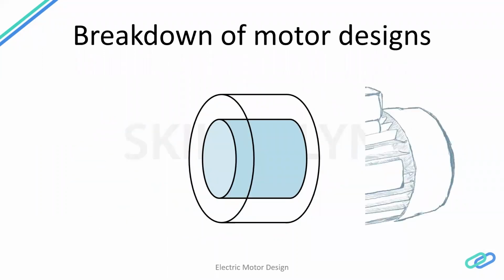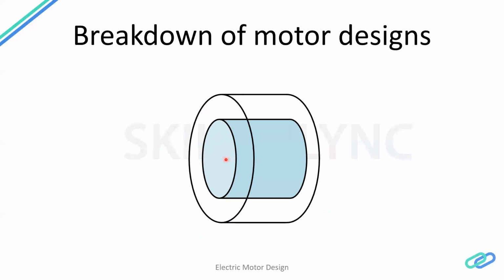What's inside is pretty much steel. You have a rotor and then a stator. The stator has coils, anything that is not moving, right? It has coils that carry currents, which develop a rotary magnetic field. And then the rotor, if it's a permanent magnet motor, has permanent magnets in it, so they develop their own magnetic field. The stator has its own magnetic field. Eventually, they both lock in to develop a rotating magnetic field that will rotate the rotor. So that's the basic principle of electric motor design.